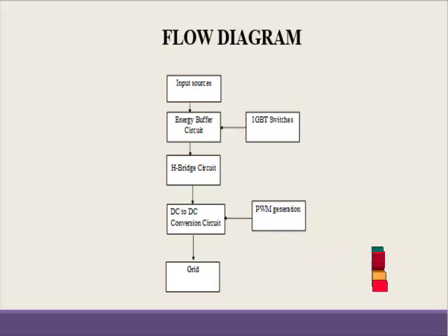So we mainly use the IGBT switches. The IGBT is a cross between the conventional bipolar junction transistor and the field effect transistor. Both are ideal semiconductor devices, and the IGBT takes the best part of these 2 types of transistors: high input impedance and high switching speed. We use the IGBT switches mainly in the H bridge circuits.